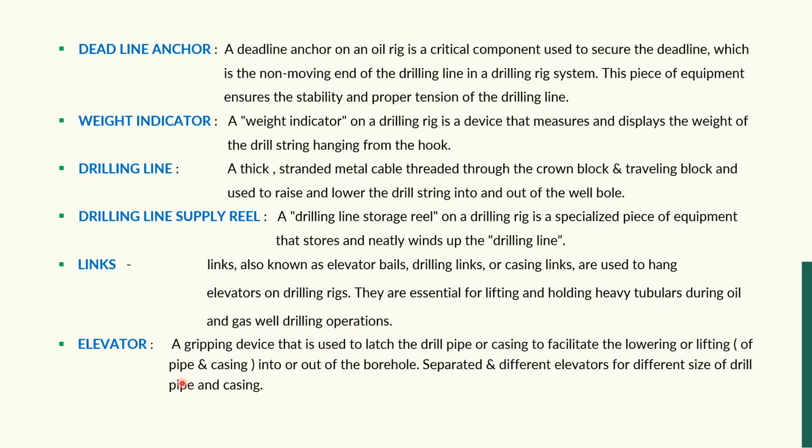Okay, when we need to raise or lower the drill pipe or casing or tubing, we use this elevator, which is connected to the link. Elevator. Elevator is a gripping device that is used to latch the drill pipe or casing to facilitate the lowering or lifting of the drill pipe or casing into or out of the borehole.